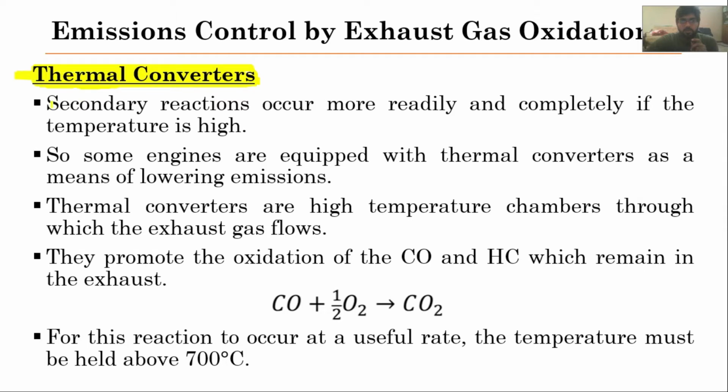So in thermal converters, as I mentioned earlier, during the expansion stroke, or maybe in the exhaust stroke, or even after, when these exhaust gases have reached the exhaust manifold, there may be some reactions occurring which will convert some unburned hydrocarbons and carbon monoxides into carbon dioxide and water vapors.